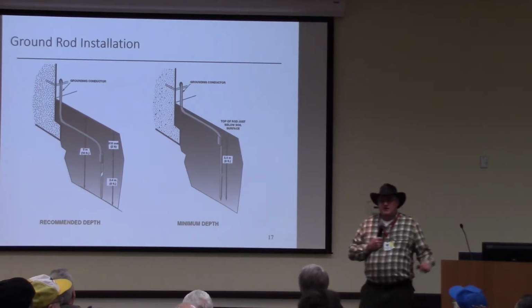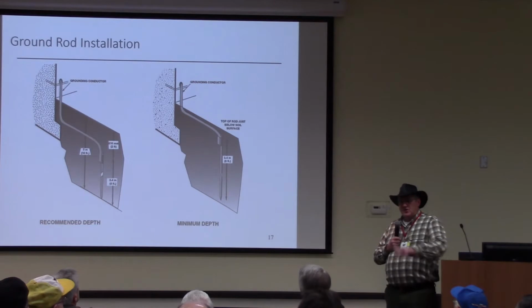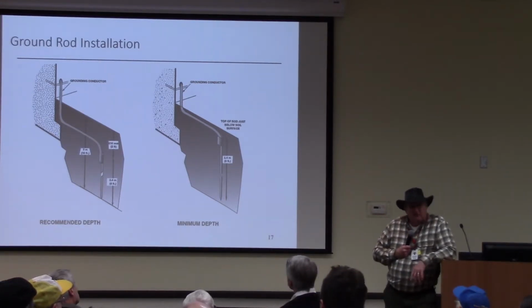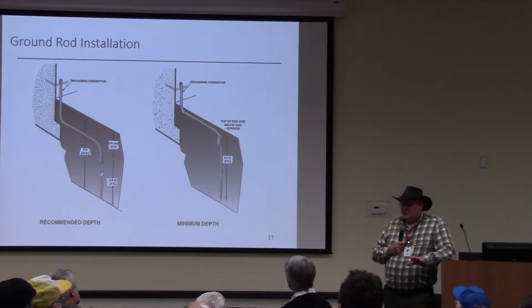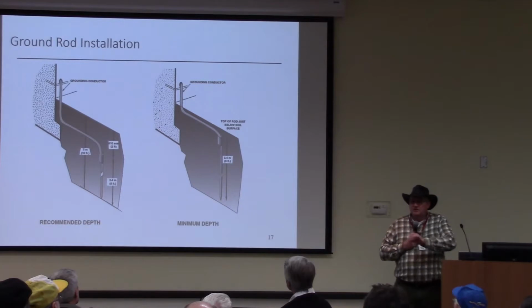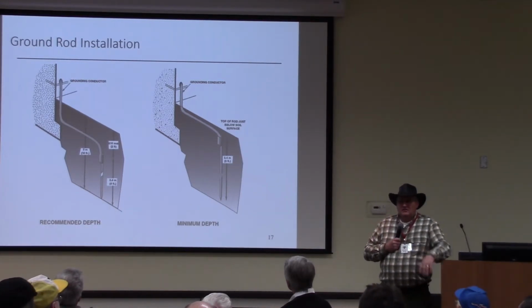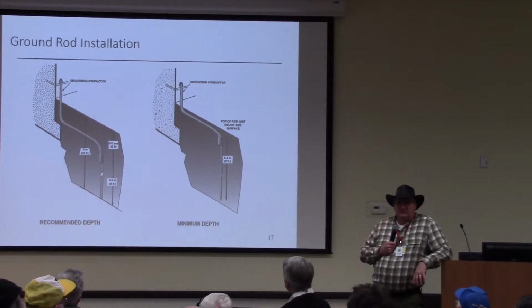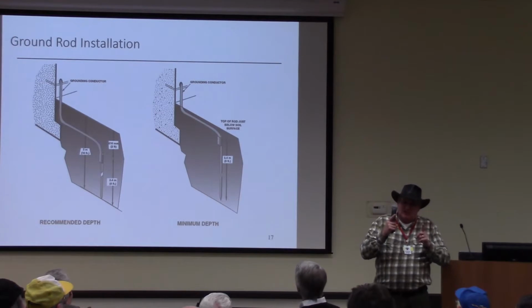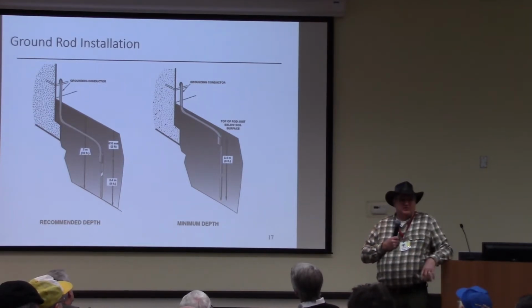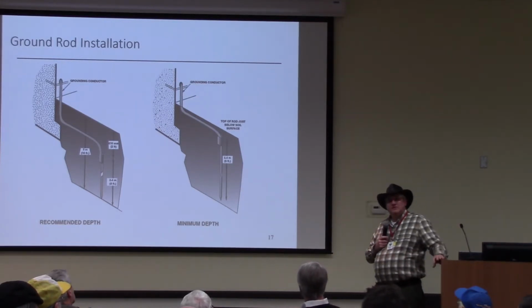Well, what that would do is, if all the leaders did attach, and let's say you took it, disassembled it, and you laid the cable in the back, and just laid it on the table. Let's say the lightning strike does attach to your antenna. The circuit is not closed yet, right? So let's use that million volts we said earlier, prior to the strike. In this thought process, that would make that gap have 1 million volts across it. Basically, it puts all that potential prior to the strike across that gap. Like I said, we're talking concepts here. So you're going to have a much higher voltage than the 225,000 volts across that gap, and it can jump as much as 50 feet.